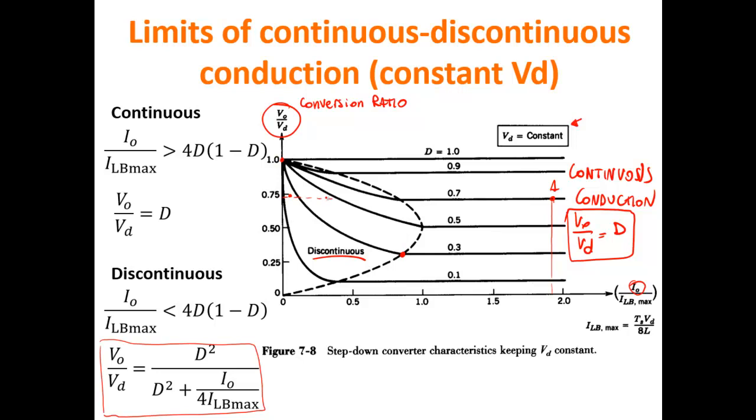And the controller has to be extremely fast because here the duty cycle is 0.7. Okay. When I go here, the duty cycle is, I don't know, something probably 0.2. So the controller has to sense rapidly the variation of the current and change rapidly the duty cycle. And that is typically done with an embedded processor that controls the switch, that senses the current and adjusts the duty cycle as a consequence. Okay?